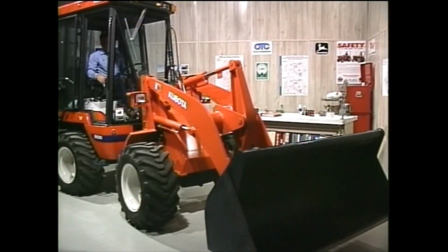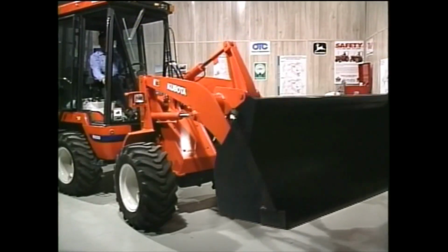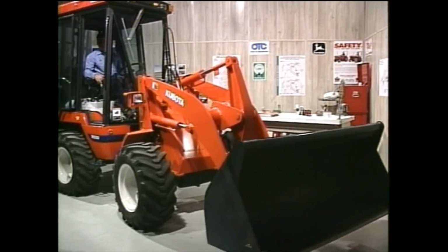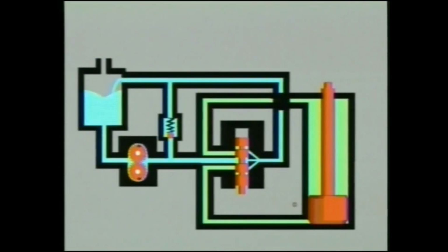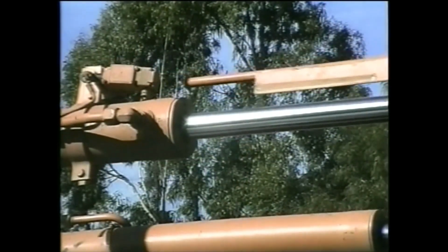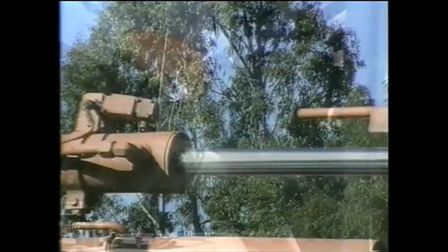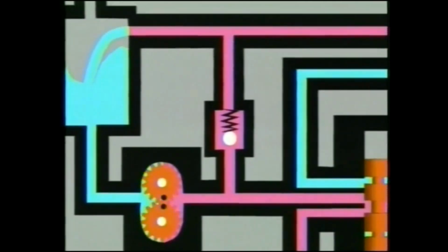In an open-centered system, when the spool in the directional control valve is stroked, meaning pushed or pulled, hydraulic oil is directed to the piston in the cylinder. When the hydraulic force under the piston becomes greater than the piston load, the piston will move up until the spool is returned to the centered position or the piston in the cylinder reaches the end of its stroke. If the spool is not returned to the centered position, excessive heat will develop when high oil pressure is relieved through the system relief valve.